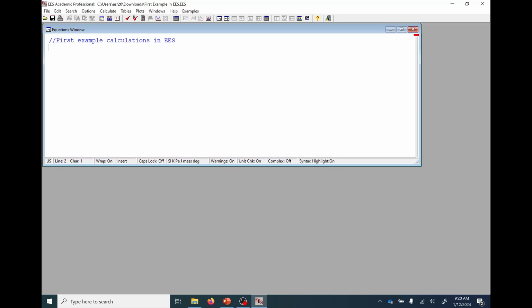You can give your comments in a couple different formats. You can do / at the beginning of a line. You can have comments within quotes. So here's another comment: if you start your quote, you go quote !. You can give a different colored comment, which can sometimes be useful when you're trying to organize the different sections of a large program. And if I hit Control Save, it will automatically do the equation check and update the coloring or formatting of my different lines here. Okay, nothing too exciting so far.